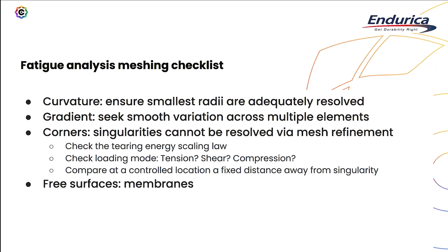Cubit does have a tool set for setting up these membrane meshes, but we didn't look at that in this work, and like I say, we'll probably follow up with more information there. But that would be another recommendation in helping to get converged results for your fatigue analyses.